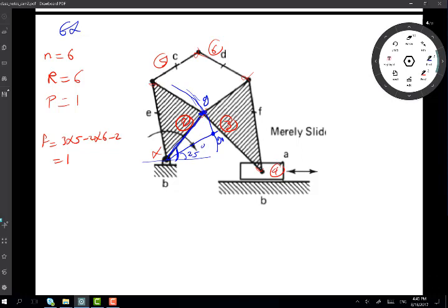So the difference between those examples and the other ones is that I have laminas for the links, like for 2 and 3. And it's because the link is rigid, so it's quite simple to solve the problem really. Like if I have point G here, I need to find this point. If I call it H, for example, the new position of point H, correct? I can find from point G, and then once I find the new position of point H, I can draw the lamina again, which represents link number 2.